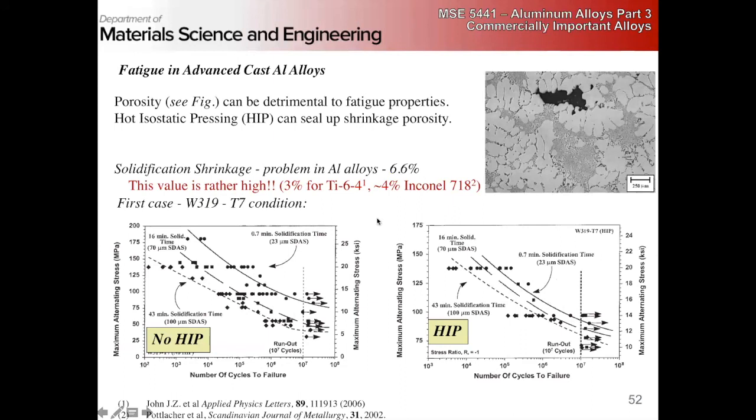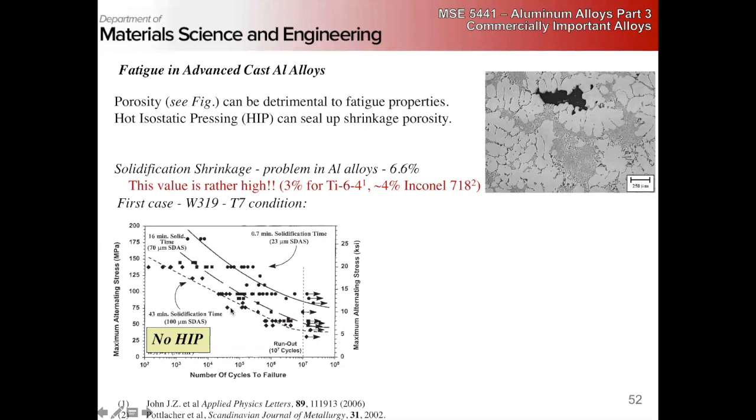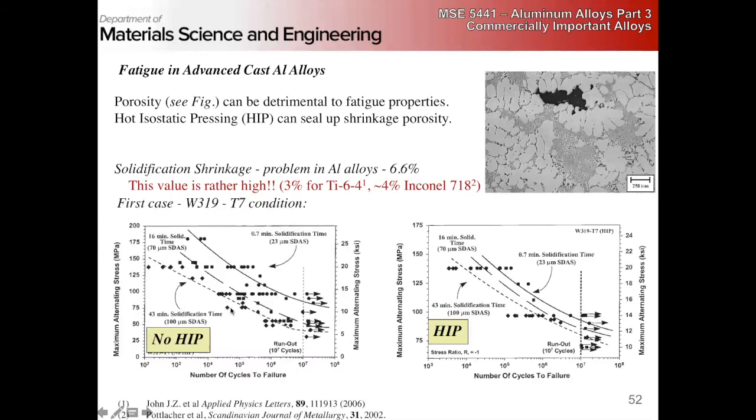All right, and these are the low stress thermomechanical cycling fatigue samples that come from the number of times you start and stop your engine. This isn't the high cycle fatigue of the vibrations.